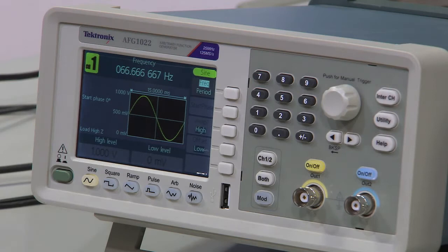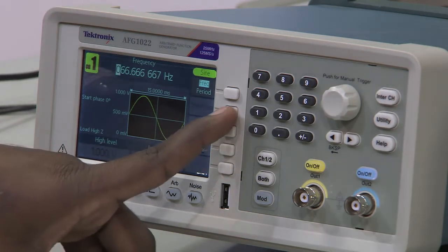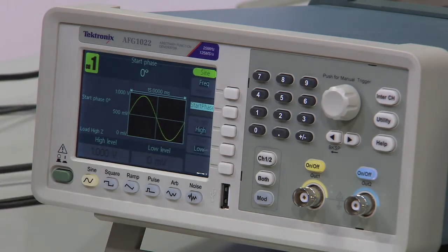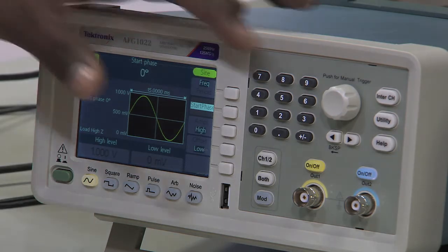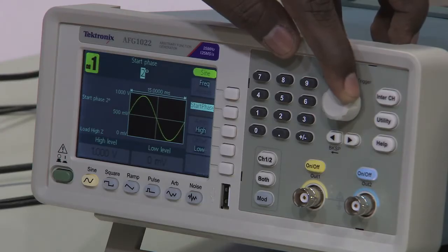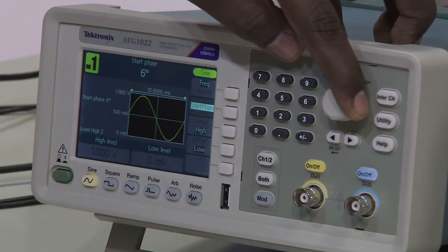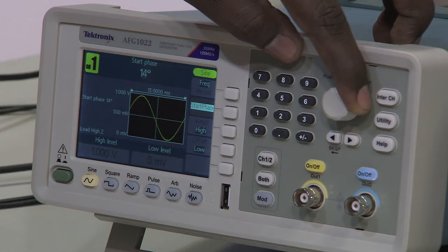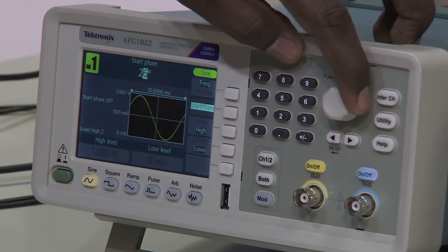Excellent. Now, we go to the second one. The second knob is the start phase. We have seen in the inverting amplifier, the non inverting amplifier, and in oscillators what the input phase is, what the output phase is, what the start phase is, whether it is 0 degree, 90 degree, or 180 degree. You can change the phase of the signal by giving any value that you want. Suppose we are changing the phase, you can see there is a change in the sine wave, the phase of the signal, and right now it is 15 degree, 16 degree, and you can see the change.